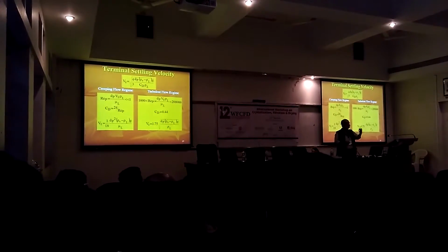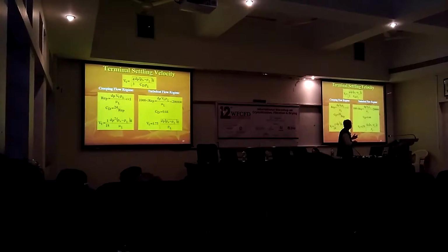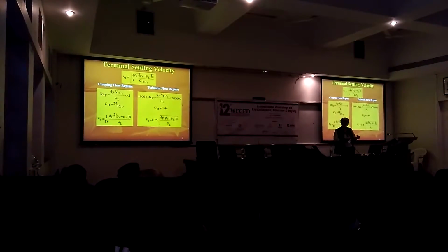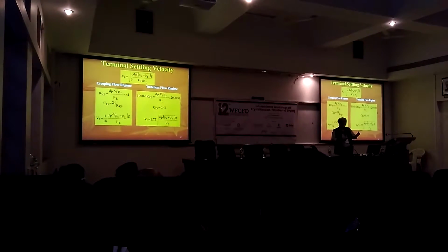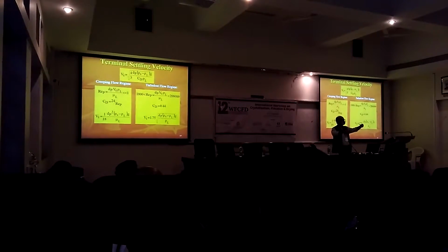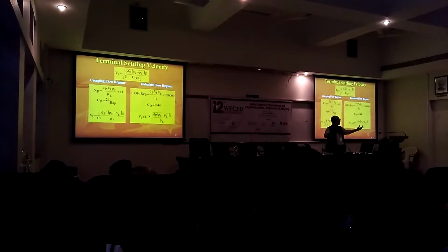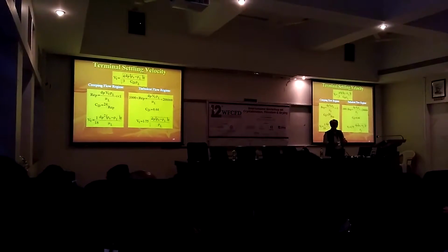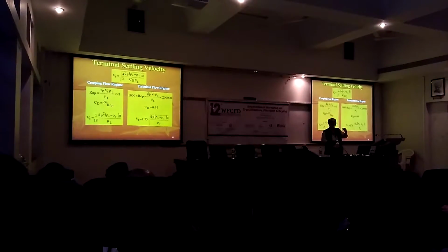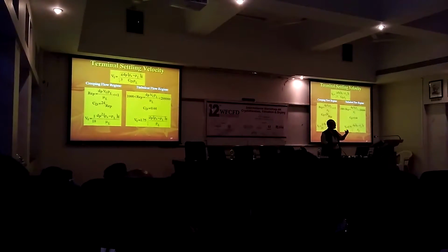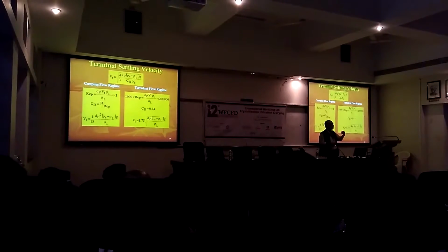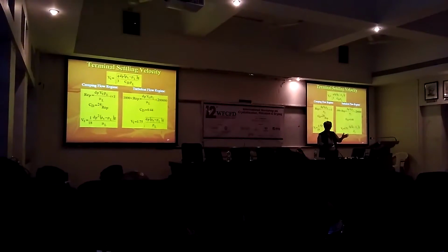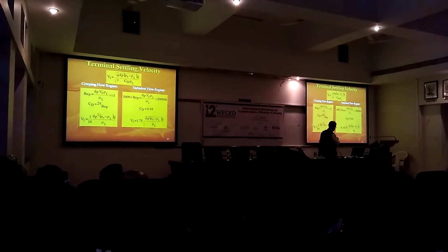So, when the nuclei are getting formed, their nuclei may be in this particular regime, in the laminar regime or a creeping flow regime. But as they grow, so you will find that keeping suspension of nuclei is relatively easy. But as they keep on growing, their settling velocity is going to increase. And if you do not take into account this increased settling velocity, you will find as the larger particles get formed or the crystals grow, these particles will tend to settle and you will get a completely different crystal size distribution than what you desire.